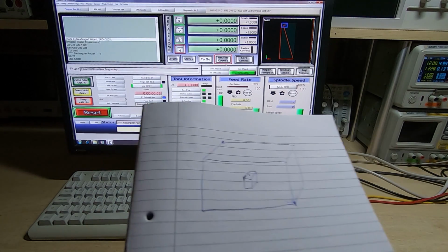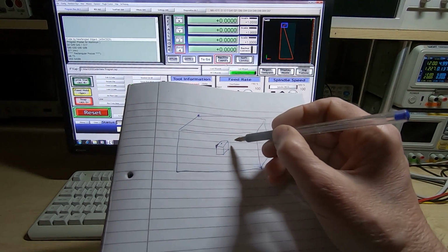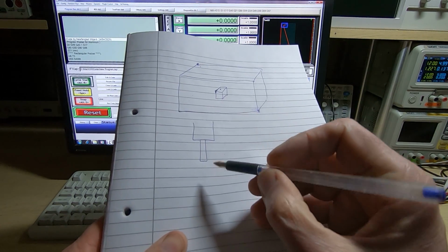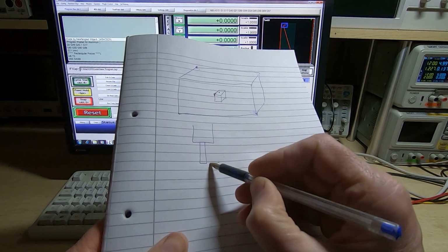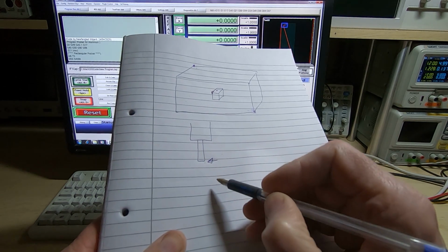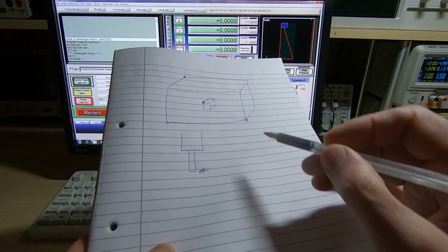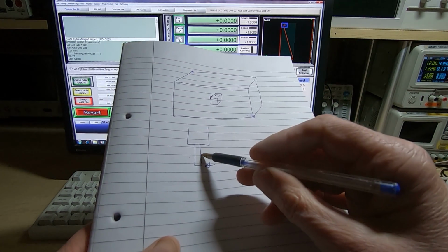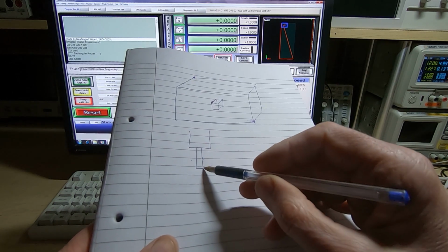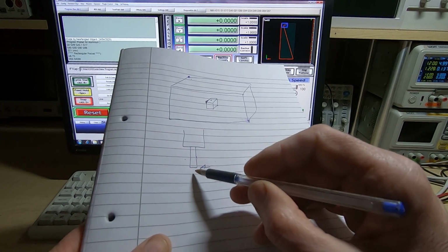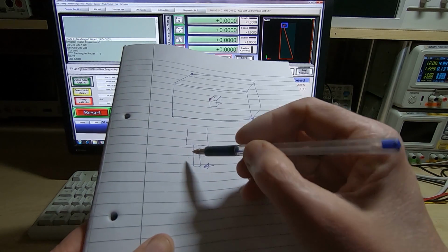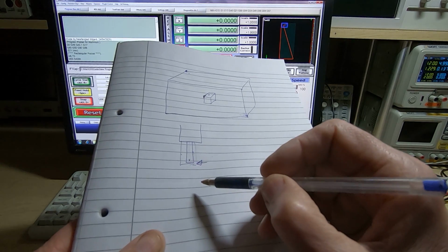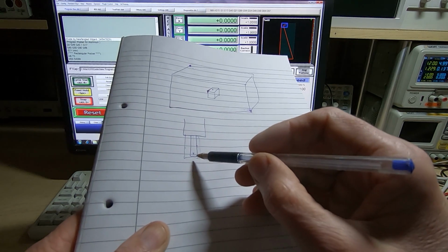The problem is, of course, that the mill needs to know, if we have the tool holder and a tool sticking out of it, where the tip of the tool is. Now, the X and Y isn't too much of a problem because once we've established that, the mill can keep track of that. But if we change the tool, we might change it for one with a different length. Now, the X and Y will still be centered in the center of the new tool, and if we put a bigger tool in, the X and Y will still be centered in the middle of the new tool in the X and Y axis.